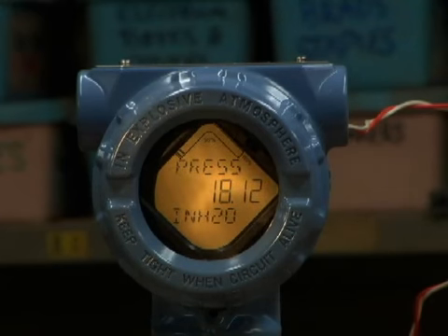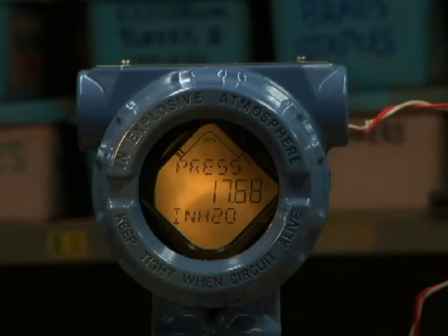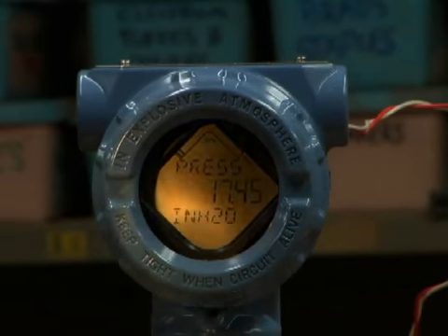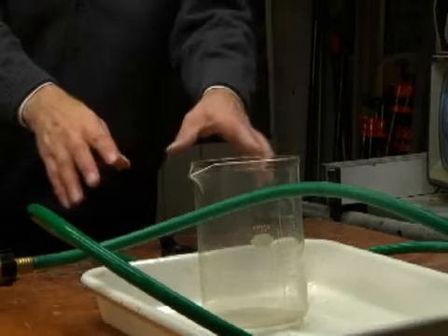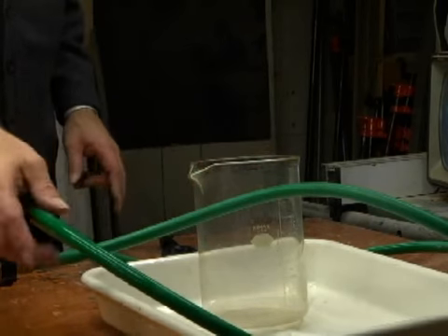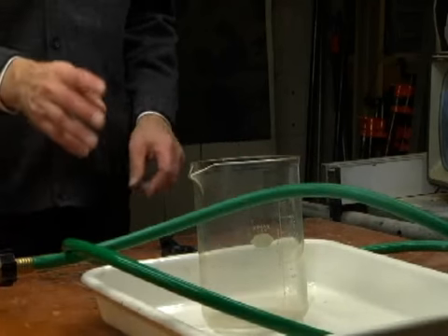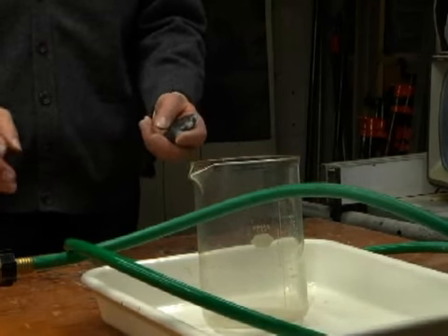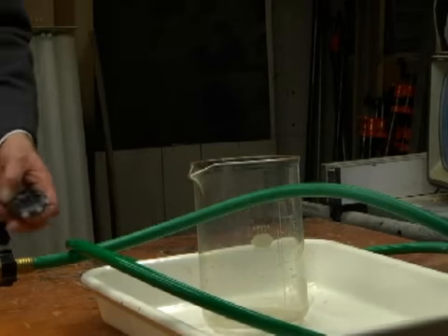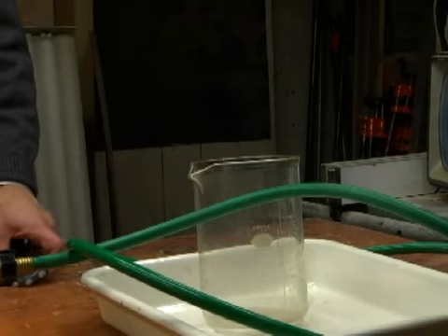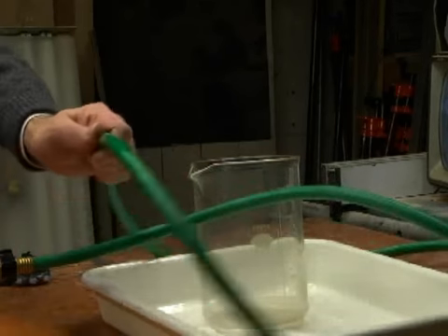So it jumps to just over, right about 18 inches of water with the flow what it is. Now, that really doesn't tell us anything because we really don't know what is going through the pipe at this time. So let's try a little calibration. So over here what I have is a nice 2-liter beaker, and I'm going to use the hose to feed into that. And as soon as the flow gets stabilized, we'll use a stopwatch to measure how long it takes to fill the 2-liter beaker. And that will allow us to calculate the flow rate. So let's turn this on and see what happens.